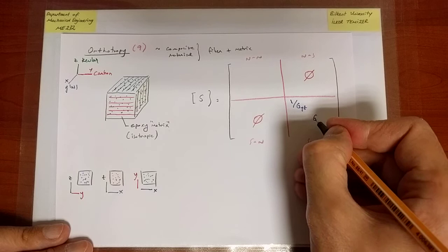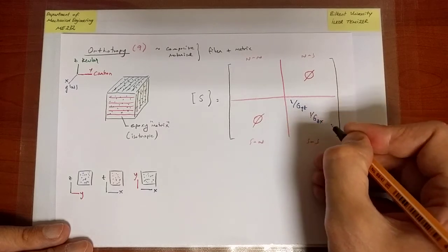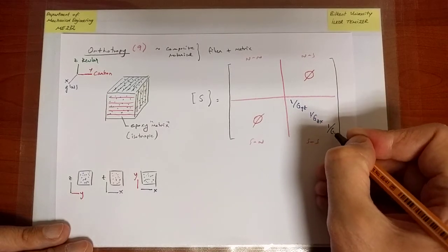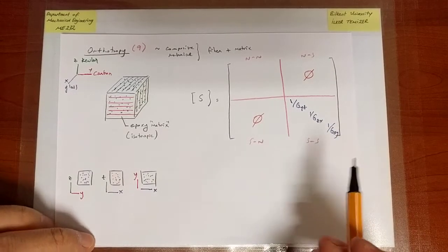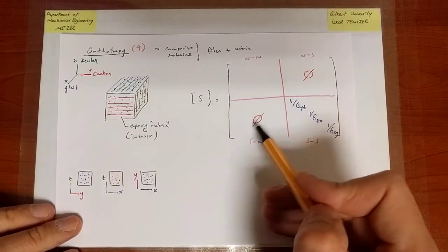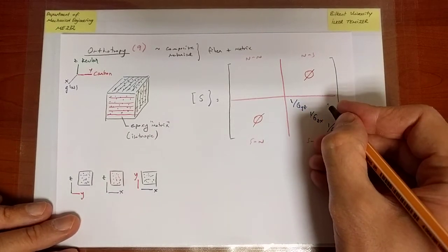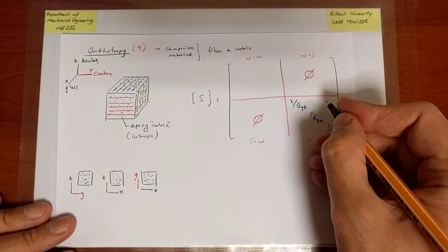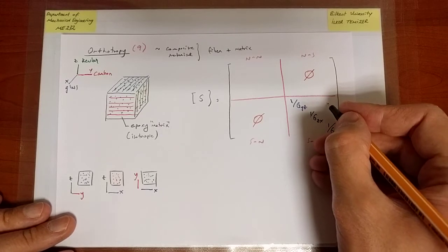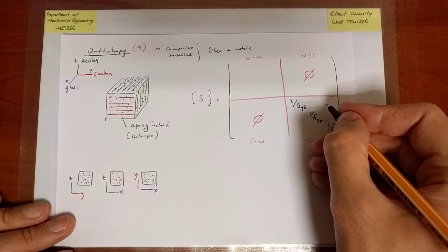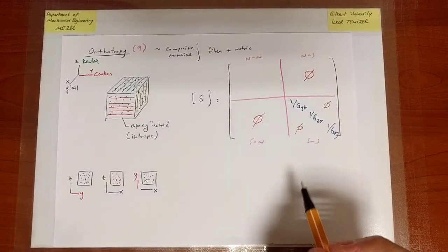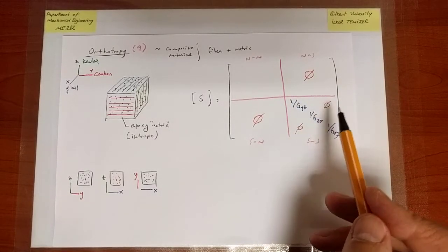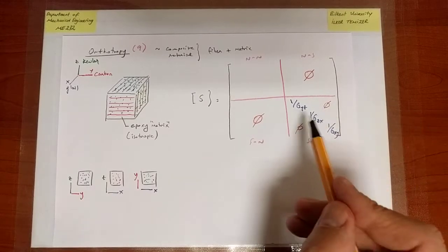The second one is ZX, so it's 1 over GZX. And the third one is going to be 1 over GXY. Okay? And it turns out that, again, because of the orientation of my coordinate system or of the carbon fibers with respect to this choice of the coordinate system, the out of plane components here, out of diagonal components are 0.